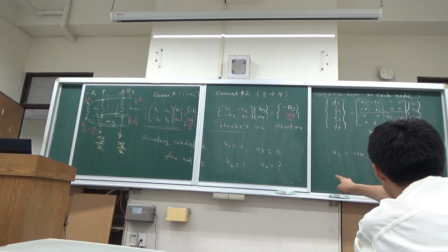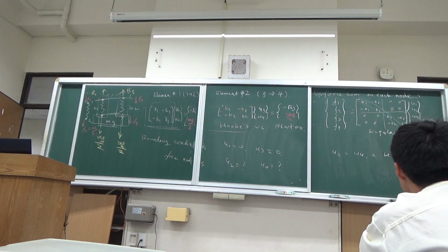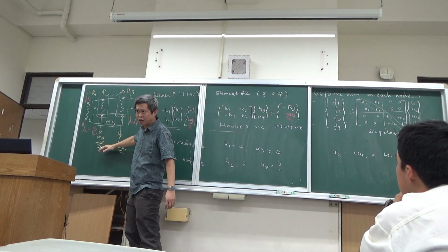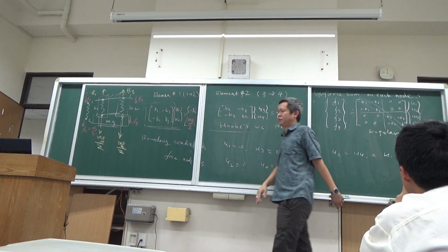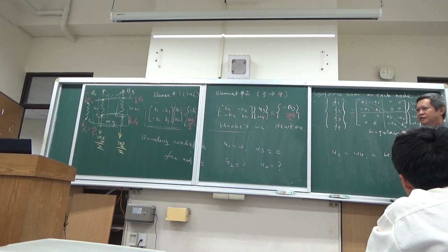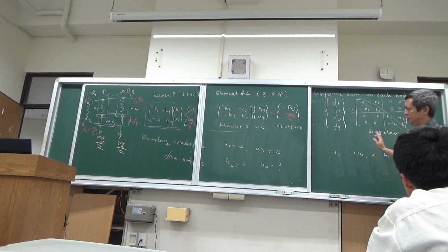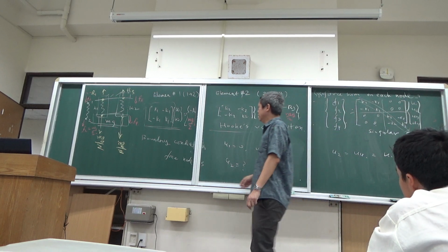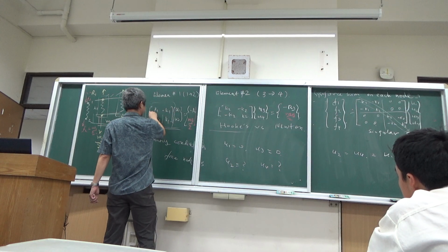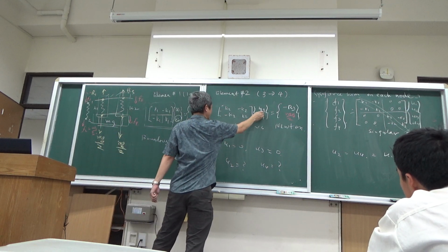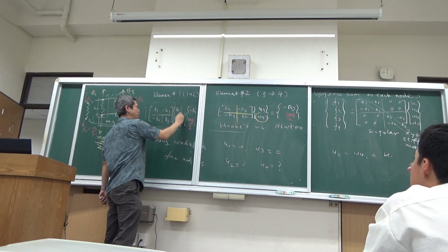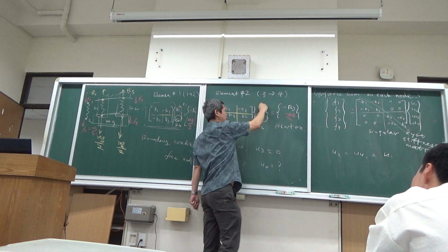That one is U4, right? Yeah, U4. So this is assuming that they are moving in parallel downward. Okay, that's fine. But what happens if it's not moving in parallel? You need to write the third equation. I'm coming back to that later. So let's assume this is true. Then what you can do is identify your free nodes. This is free, this is free, and it happens to be equal to U equal to 0.